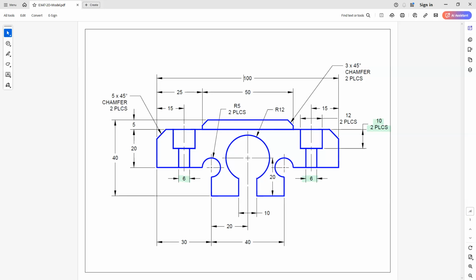Some of the other things that we need to look out for is that we don't do any double dimensioning, or, you know, just basically repeating the same dimension. For example, here at the bottom, we see that both of these numbers are going to equal 70. And we should be able to deduce that the distance that goes from here to here should be 30 as well, right? Because if this is 70, the overall length here is 100. We don't have to tell them that, hey, that number is 30. They should be automatically able to figure that out.